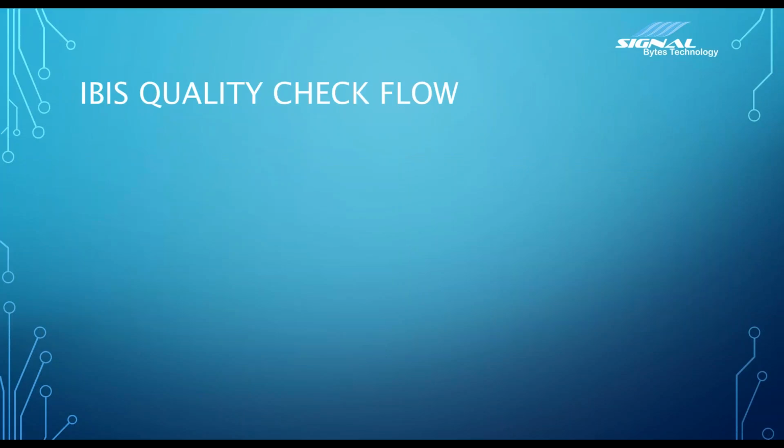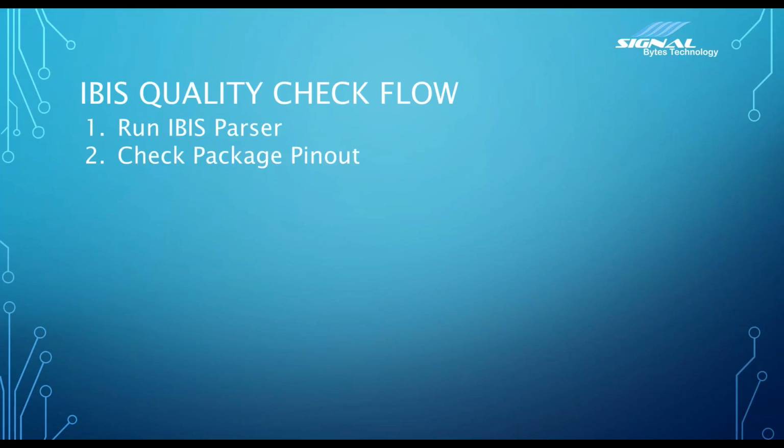Like I said in the last webinar, I went over what an ideal quality check flow is. The first step is to run the IBIS parser, and this is your first line of defense. But you don't stop here, because the IBIS parser is more of an IBIS specification compliance checker, just making sure that everything that needs to be in there is in there at a basic level. But there are lots of things that it can't check for, and there's a lot of ambiguity in terms of checking something and determining whether that's a quality model or not. We'll take a look at that today.